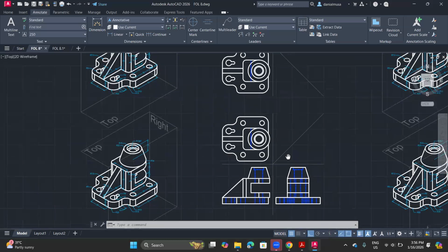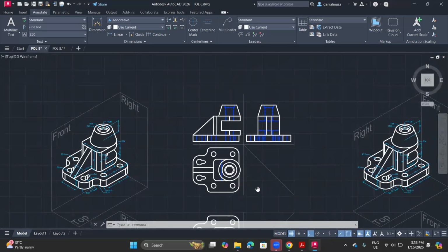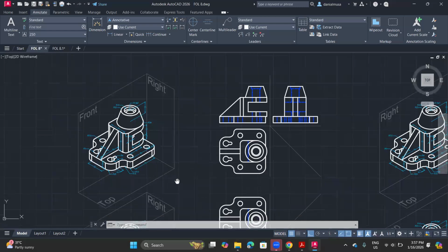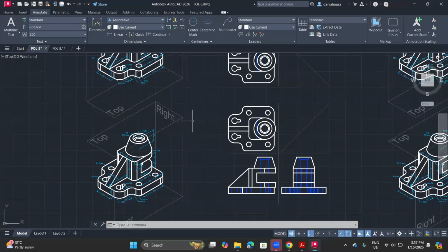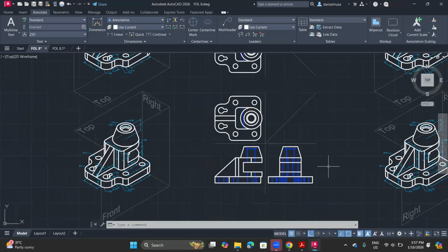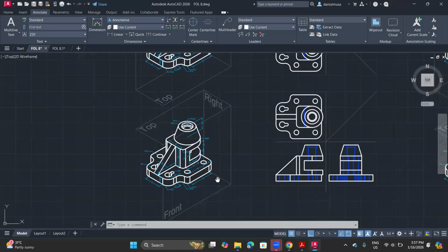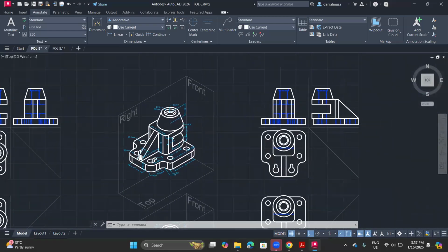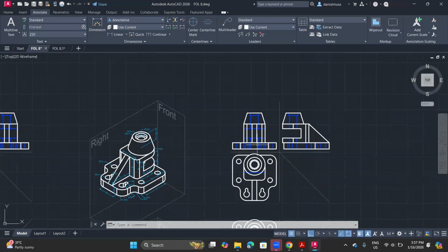If you see the front and the top, they don't have any difference, right? But the side view is really different, because you look through from here, so it is this face. But for here, it will become this side, because you are looking through the paper like this, so it changes the side view to another side. Because we set this as the front, right? But if you want to change the front view from here, it will become like this. The front view will change to here, and the right view will become like this, because you look through here.